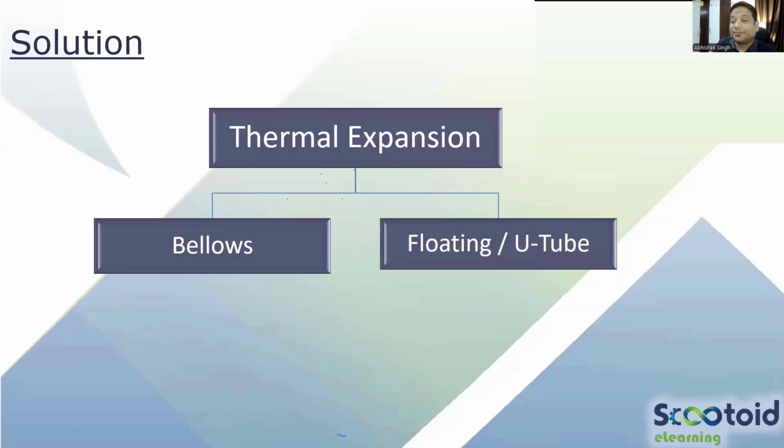Okay. So normally the oil and gas industry or any critical industry will not prefer bellow design. Why? Why normally in oil and gas or any services which are critical, very high pressure, do we not prefer bellows? They are very much prone to failure. Okay, so they are prone to failure, right? So it is not preferred, but if you don't have any option, then you have to do it.